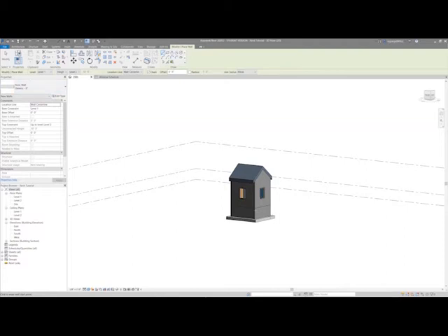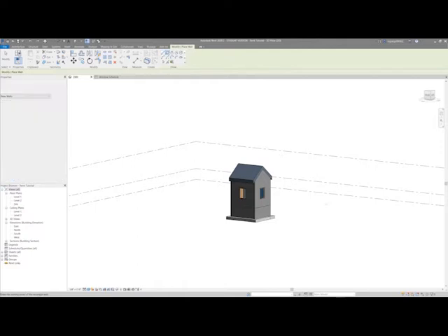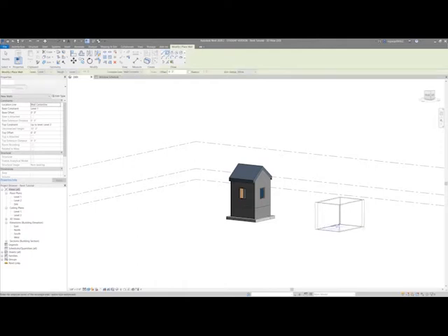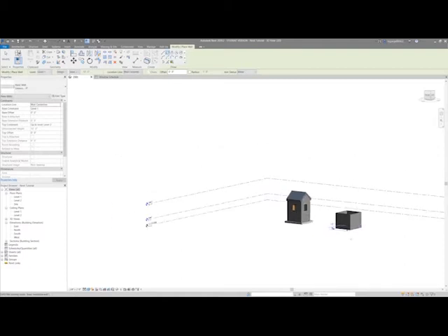And then you can associate the wall with the level base. The level height will be 2. And the location line, we'll get into that a little bit later. And then just the form. So I can make a line, a rectangle. We'll start with a rectangle, and we'll just make that form. So I made that.